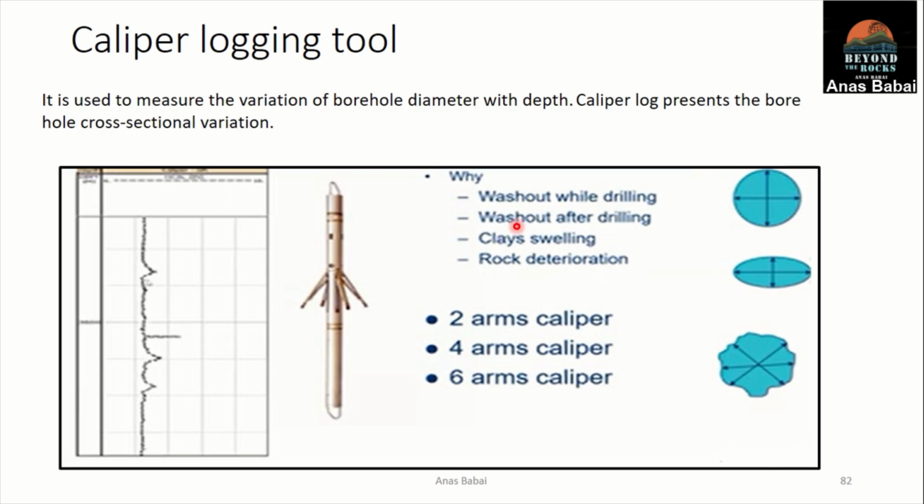Also, after we finish drilling, the drilling fluid can react with the rocks that compose the specific formation, and that can make it very loose, and it can cause some cavings or changes in the borehole section.